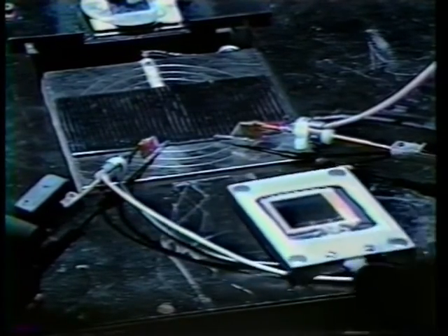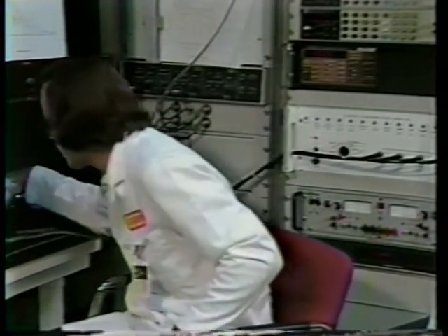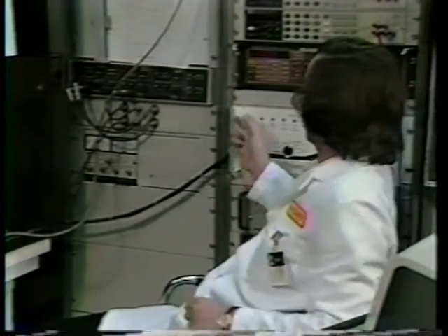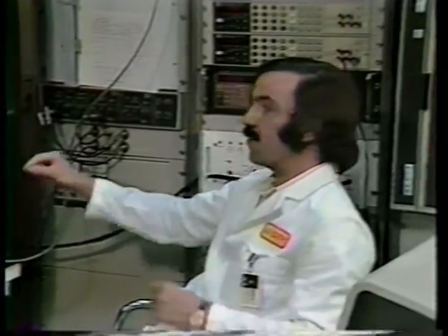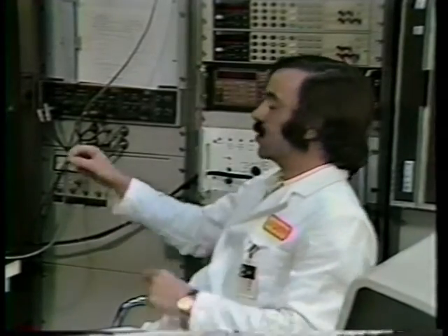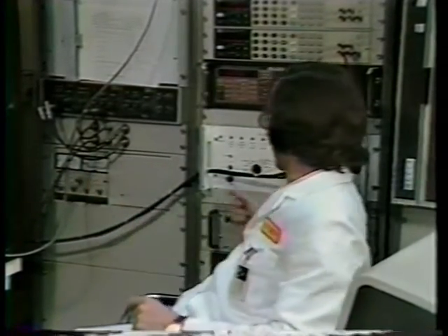Another thing which I must do in order to make efficiency measurements is make contact to the solar cell. In our laboratory, we rarely receive solar cells that have wires attached to them. So I must use probes to make contact. In addition, we have a vacuum plate which makes contact to the back of the solar cell. So now I am going to make contact with the solar cell, which I have done. And this test station over here verifies that I have made contact. In this case, I have 9/10 of an ohm across my voltage and current contacts to the top of the cell, and 1.1 ohms between my voltage and current contacts to the back of the cell.